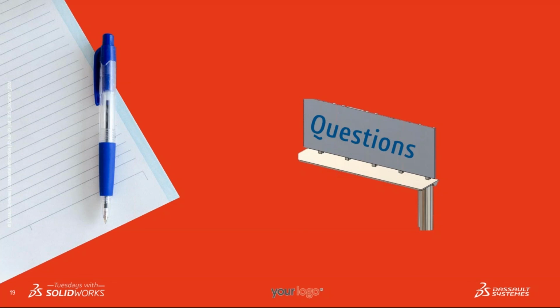Okay, we have a question here. Is fatigue analysis included in Simulation Standard or not? Can you give some insight about this question, Saleh, please? Okay. The normal fatigue plot is found in Simulation Standard, but for more complex fatigue types of loading, like complex loading or non-periodic loading, you can move to a more professional solution for fatigue input boundary conditions. You can go through SolidWorks Simulation Professional software.